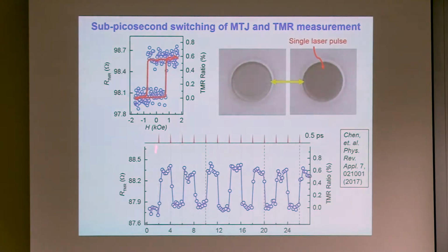They agree really well in terms of the TMR ratio. The absolute resistance changes a little bit because in different experiments, every time you put the probe down, you measure a different contact resistance. But the TMR ratio agrees with the magnetic field sweeping. That tells you that you're really completely switching the top contact of the gadolinium iron cobalt layer.